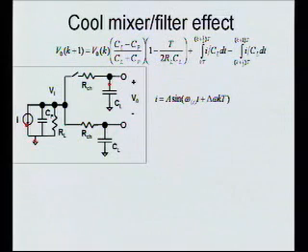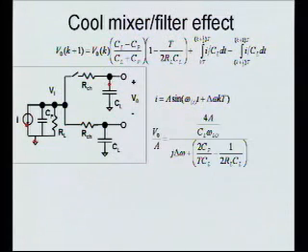Now, that's a really nasty equation, and I don't expect anybody to analyze that off the top of their head. But if you do, and you spend 15 minutes rearranging things, you discover that really the output voltage just looks like a single pole transfer function. So just to see that, basically, that's your single pole, right? There's your imaginary part, and this is your real part. This is all at the low frequencies. And there's a gain term that depends just on the frequency of your LO, and when you do all the math out, the parasitic capacitance. A bunch of things in here cancel in band.